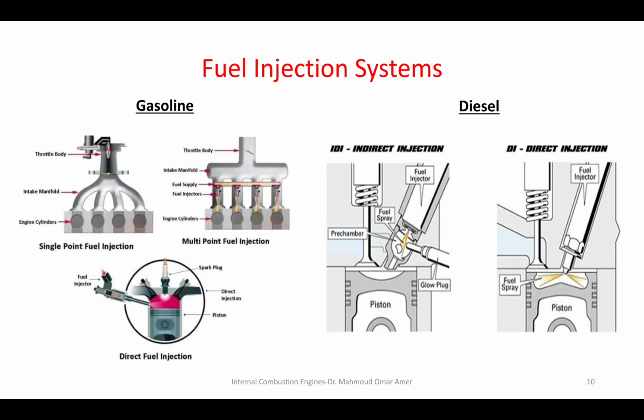What does the pre-chamber contain? It contains exhaust, which is burned fuel, and it contains part of the air, and it contains the unburned fuel. And it now has high pressure and temperature. So what happens? All these components inside the pre-chamber move back inside the main cylinder through the orifice. And again, the orifice increases their speed and increases their swirl. Okay? All these swirls that I'm talking about, what do they do to the mixture? They enhance the mixture of air and fuel, which improves the mixing efficiency of diesel and enhances the combustion efficiency.